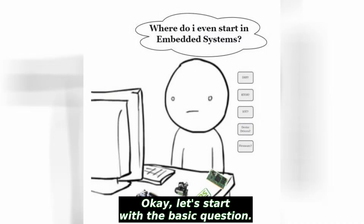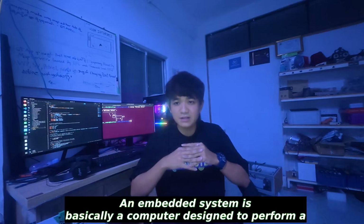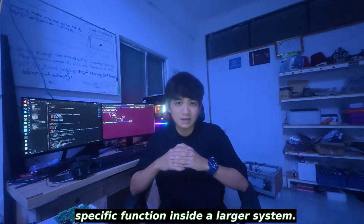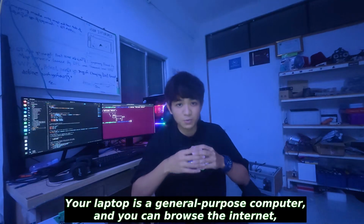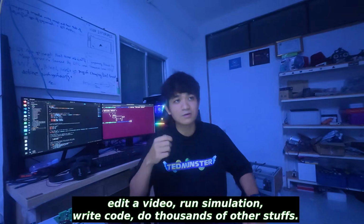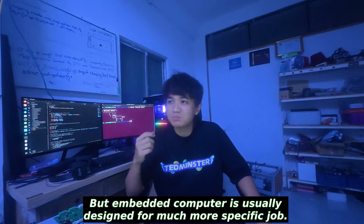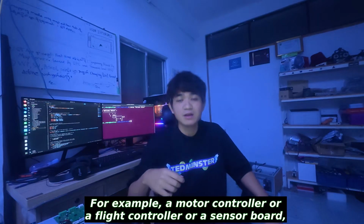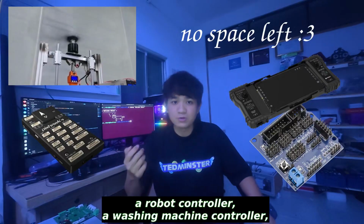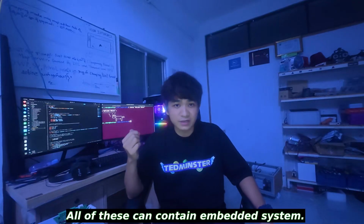Okay, let's start with the basic question. What exactly is an embedded system? An embedded system is basically a computer designed to perform a specific function inside a larger system. Your laptop is a general purpose computer, and you can browse the internet, edit a video, run simulations, write code, do thousands of other stuff. But an embedded computer is usually designed for a much more specific job. For example, a motor controller, or a flight controller, or a sensor probe. A robot controller, a washing machine controller, the car electronic control unit, all of these can contain embedded systems.